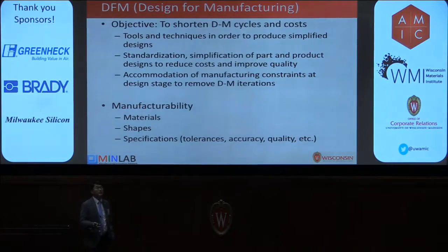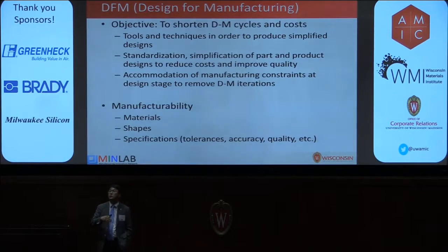So in big manufacturing companies, they practice design for manufacturing. How many of you have heard about design for manufacturing? So you know that, right? Traditionally, the designer comes up with the design and sends it to manufacturing. Manufacturing reviews it, and a lot of it is not manufacturable, or is expensive, or is just too much effort. So they send the design back to the designer, who has to modify it, and they iterate this cycle several times.